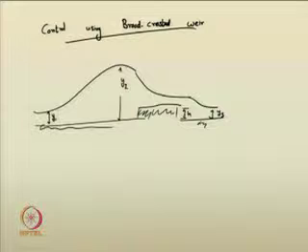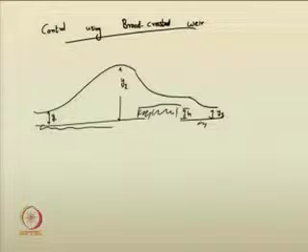That is, you are having a subcritical flow here and it will just slow down, and it can reach up to the critical flow. That is the requirement. So, using the specific energy theorems, you can easily devise what should be the depth of flow over the weir, broad crested weir and all. Again y3, so that we do not have influence of tailwater depth on the flow. That criteria is what is suggested.